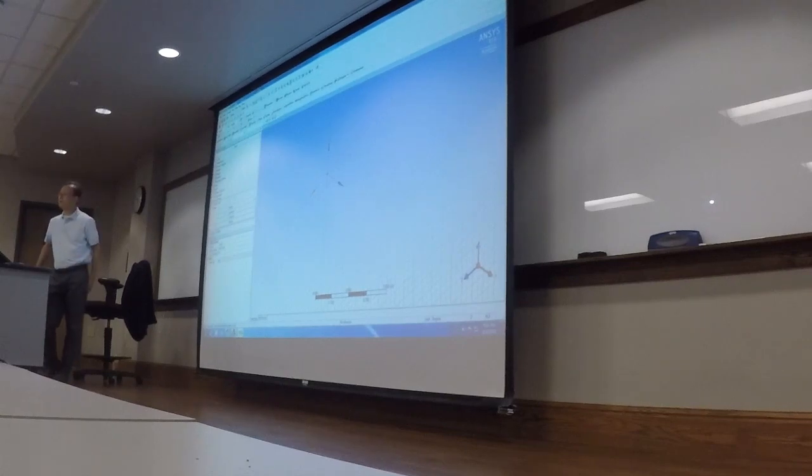Let's take advantage of the symmetry of the geometry. So let's only do half of that. So we'll have this 2-inch pipe, but only half of that. Well, once we create this arc, close it, click on line. All right. Now it's closed. So the next step, we're going to extrude.